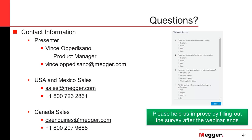And so our history, our experience tells us that if we're not sure, we simply demagnetize again. And we've given you the ability to demagnetize all three cores just in case, and we do so in the proper way. Everything we've done in our software is totally automated to our experience and understanding of demagnetization. And so yes, there is no indicator for the state of demagnetization, because as soon as you try to measure it, you're affecting it. So you may make it worse, or you may make it better, just by trying to measure the state of demagnetization. Not a simple subject either.